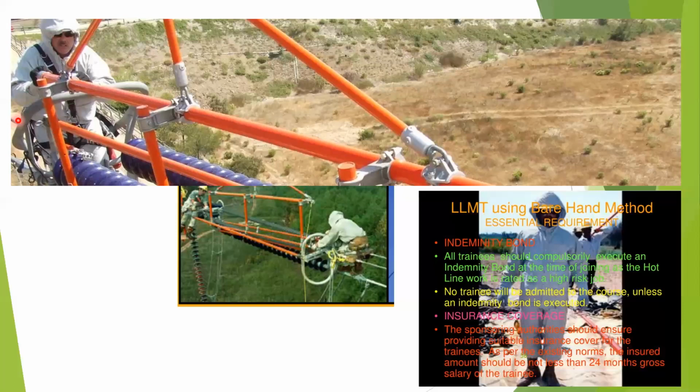So this man, I suppose, is more than 400 kV due to the number of insulators. It may be sometimes 780 kV insulators. So bare hand operations, of course, is easy for higher voltages than 400 kV, because your sticks cannot be handled at such a distance, and it's very difficult to keep the safety clearances. So bare hand operations are better.